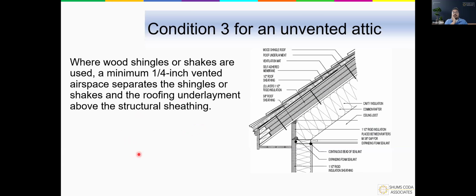Remember how we talked about wood shingles needing some ventilated airspace here? We definitely see a different tack on that. And again, this goes back to a change where our finished roof product actually influences the way that we're able to insulate this properly. And as you can imagine, you can build this with the correct insulation, and then because of a hailstorm, you might be stripping off the roofs, and somebody says, "Ooh, I'd love a wood shake roof